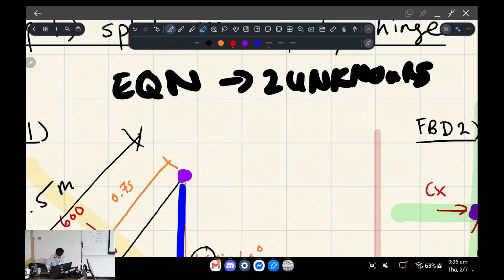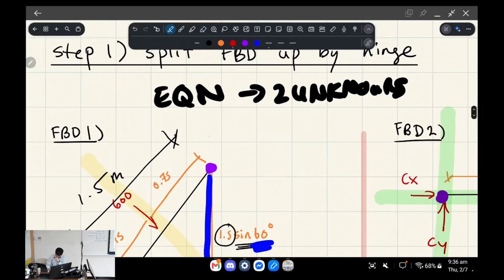Let's just go down that rabbit hole for a second. The reason it's a smart idea to break it up into horizontal and vertical components is that if we set this as some arbitrary diagonal force, you're not sure how big the horizontal and vertical components are, and therefore you probably got the direction wrong.